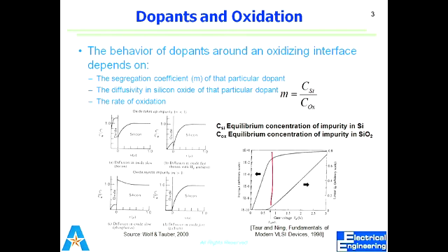But yes, the dopant is one of the causes that can affect it, in addition to very many other parameters as well. Actually, the basic Deal-Grove equation takes into account only 3 basic parameters: that is temperature, that is diffusion, and that is reaction rate. You have seen F1, F2 and F3, there were 3 fluxes. But yes, the dopant actually plays an important role, especially in case of polysilicon. Even in crystalline silicon, the higher the dopant rate or the lower the dopant rate, that will affect the oxidation rate.